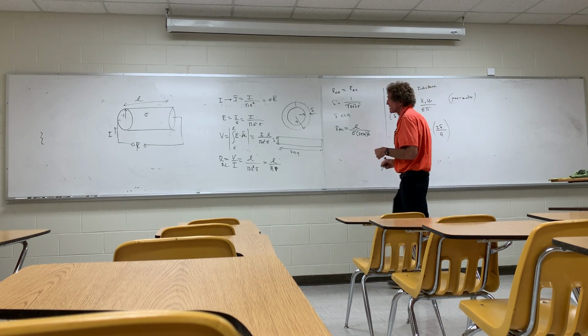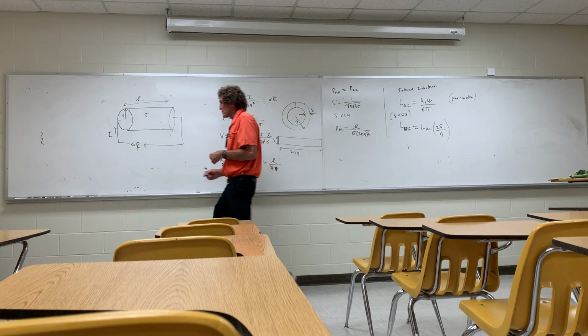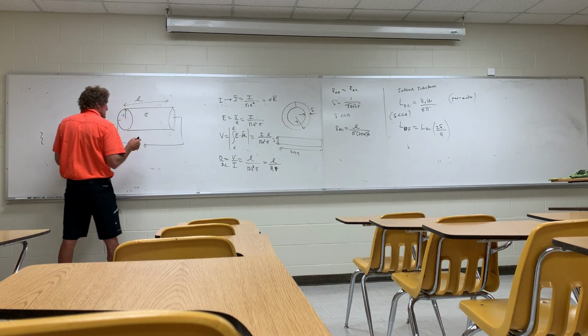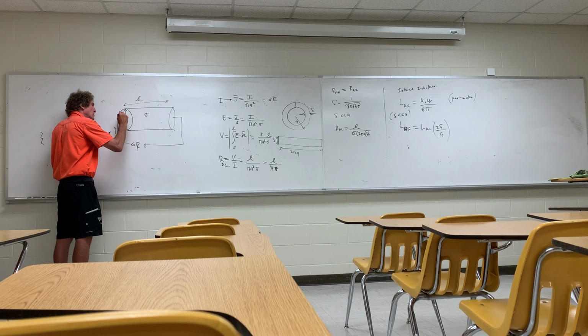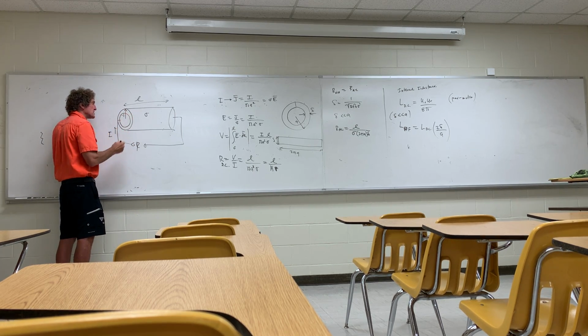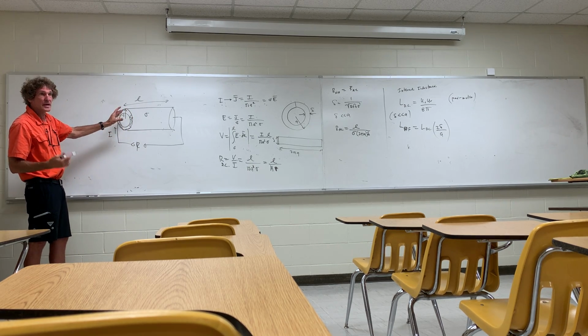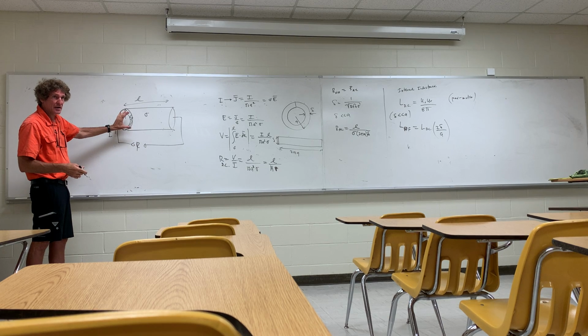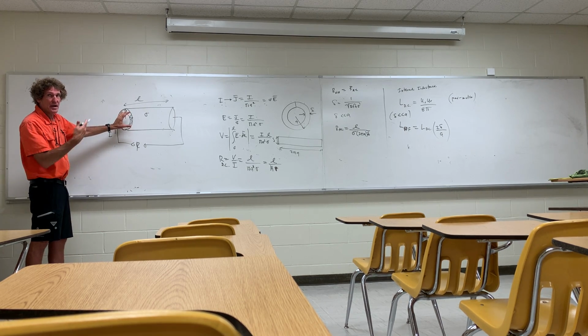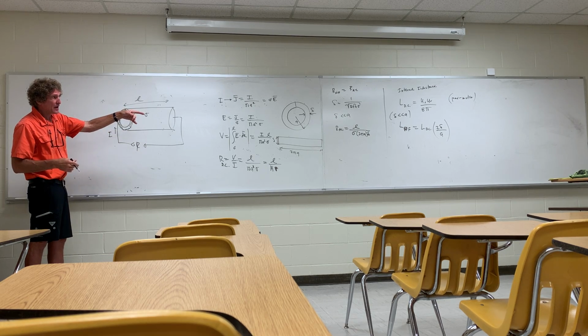Now, we can go through the proof for it, but here's what he's really doing. He's assuming all the current is distributed over one skin depth. And then he gets the magnetic energy density in there, integrates it and sets it equal to 1/2 L I squared, and then you get that L value right there, AC.